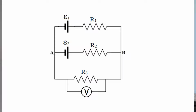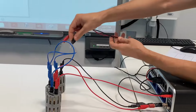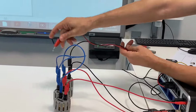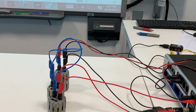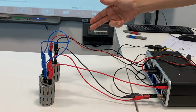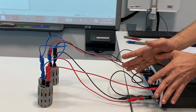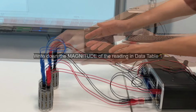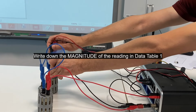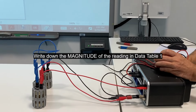So to do this on our real circuit, we will take the 2 sides of our voltage sensor and connect them in parallel with the resistor R3. So this way you are measuring the voltage difference across R3. Notice that I don't have to change anything in the circuit. Once I am done with this reading, I can remove it and move it to another circuit element, and so on.